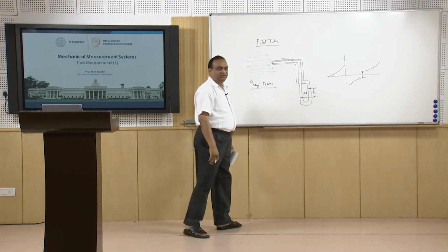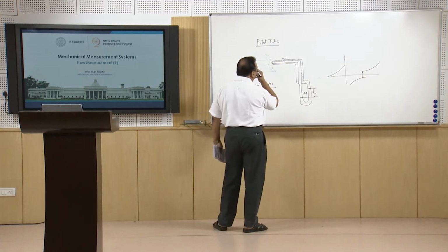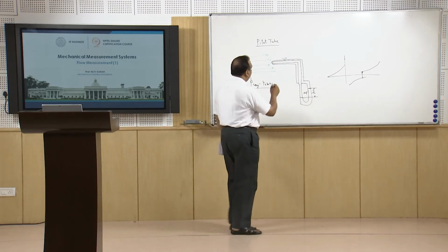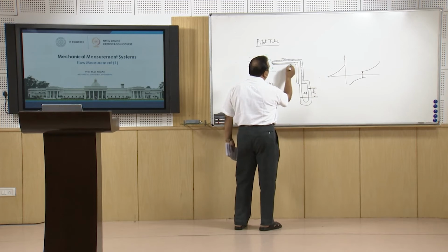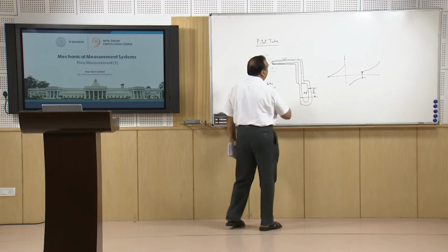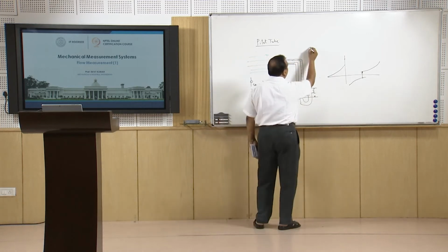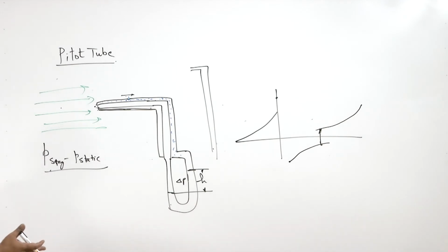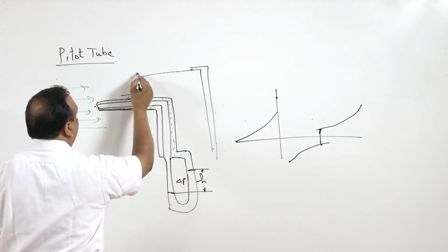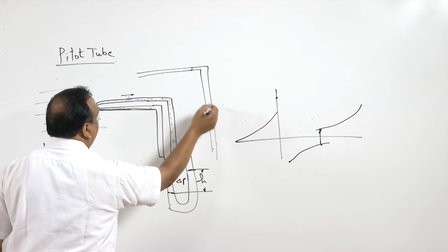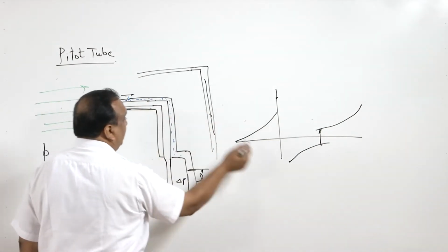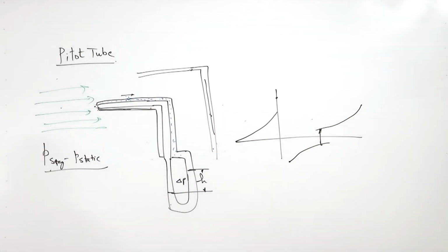And exactly this should be the position of this point. So the location of the point for the tap of static pressure is not arbitrary, and that is why you must have seen this arm or leg of the pitot tube has sufficient length. We can make it like this also. I mean, as per the principles of fluid mechanics, it should work. But normally, this length is sufficiently long to neutralize the stagnation effect by this leg, and at the same time, this negative pressure is also compensated, right?